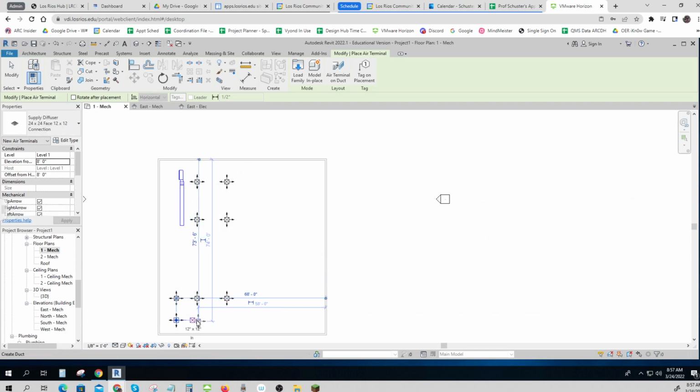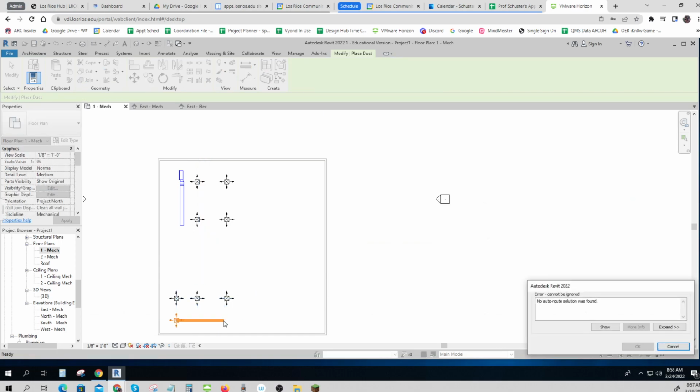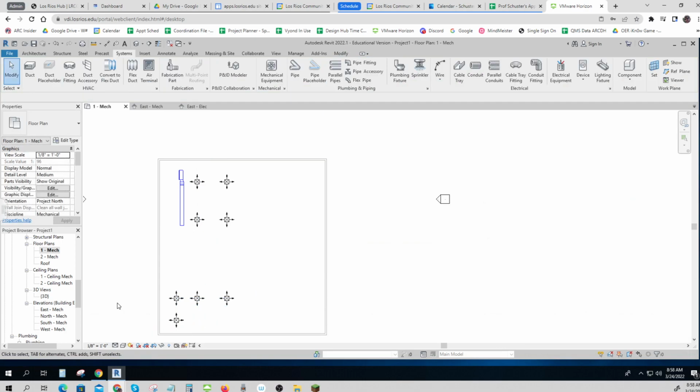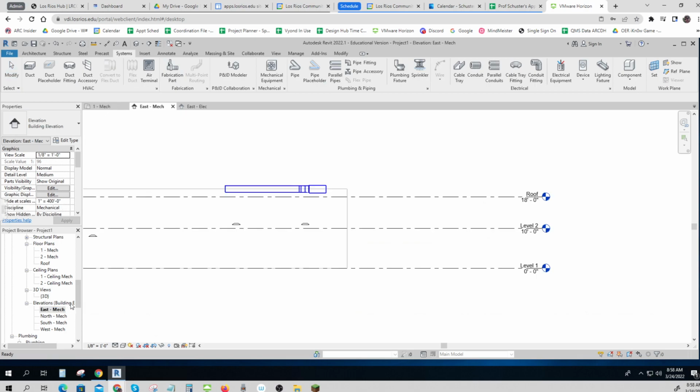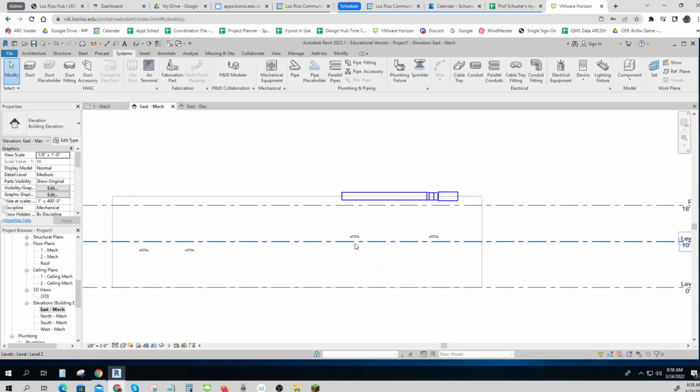And we'll size these later on. That's one of the beauties of Revit. Oop. Didn't want that. That's one of the beauties of Revit. I can go fix those later on. And you can see these ones are 11 foot and these ones are 8 foot. Once they're sized, we'll connect them all next week. So there's your brief run through of the basics of adding your equipment, adding your ducting, and adding your terminals for week 10 of Design 330.